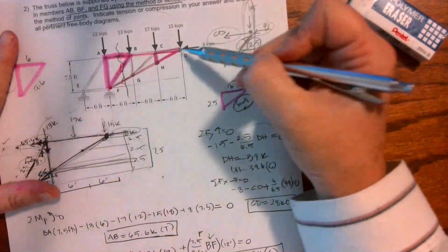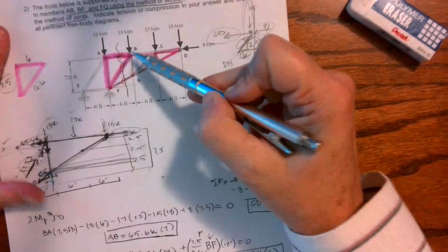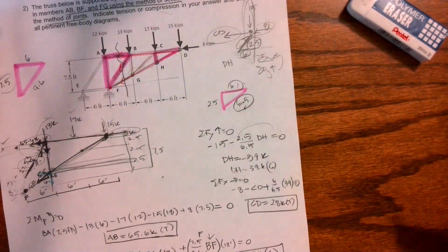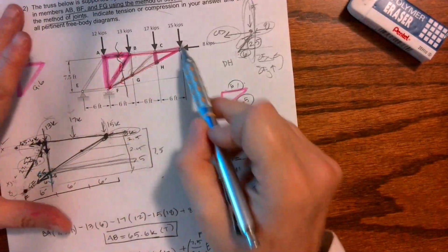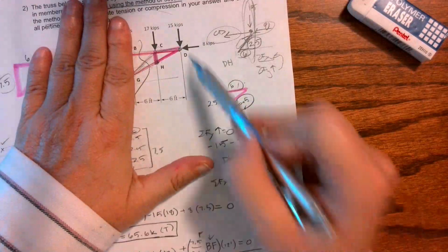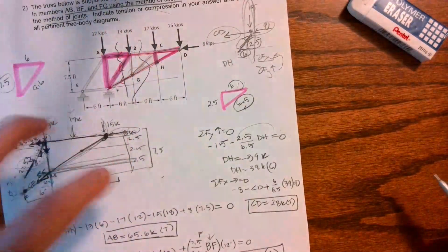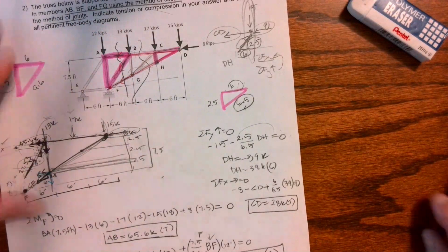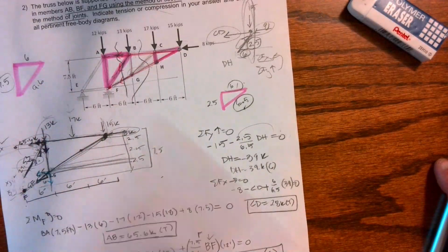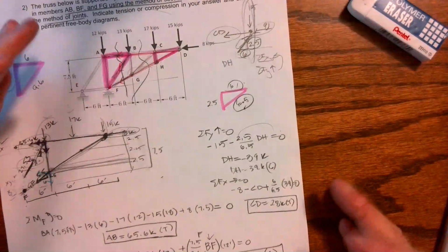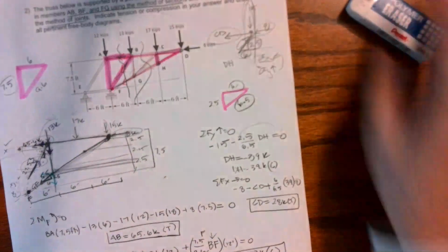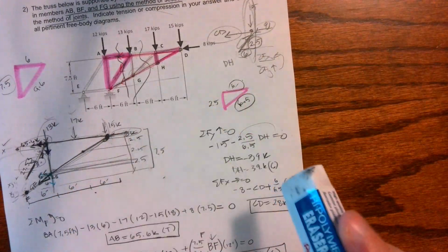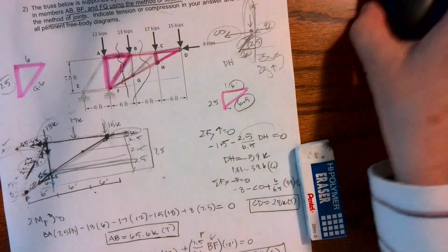So now that you know these members in this truss, you could do method of joints, work your way over, and make sure you got these values we got from method of sections. To study for this test, if you can set this truss up, cut it here, do method of sections here, work your method of joints, you get the same answer. You could literally take the same truss from a homework problem or from lecture, and you could work it 3, 4, 5 different ways. Because it's an equilibrium, it doesn't matter how you set it up, you will get the same answers. And if you don't, you need to go back and check your free body diagrams and then check your math. So that would be an example of a truss.